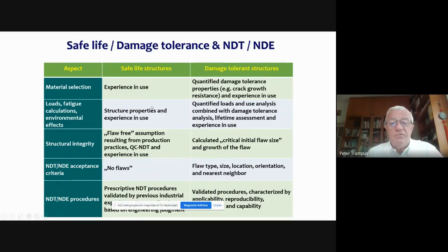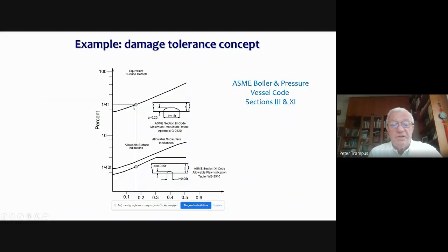And I don't want to show all the boxes, but let's see the structural integrity. In the past, our assumption was a defect-free or flaw-free structure. And in the damage-tolerant structure, there is a calculated critical initial flaw size and the growth of the flaw. So two different concepts.